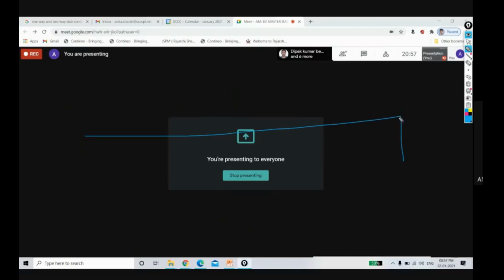आपका बेंडिंग मूवमेंट डायग्राम अगर ऐसा आ रहा है, इसका मतलब सपोर्ट पे आपका बेंडिंग मूवमेंट निगेटिव है, ऊपर जा रहा है. सो निगेटिव बेंडिंग मूवमेंट है, इसका मतलब टेंशन टॉप में है और कंप्रेशन बॉटम में. ओके, और यहाँ पे टेंशन बॉटम में, कंप्रेशन टॉप में, स्पैन पे.